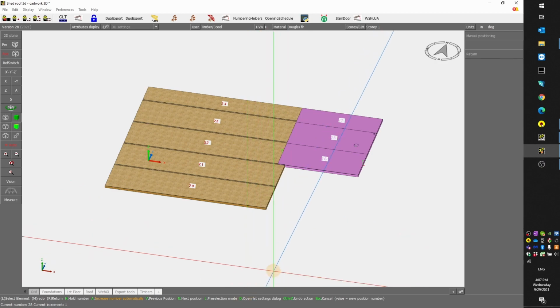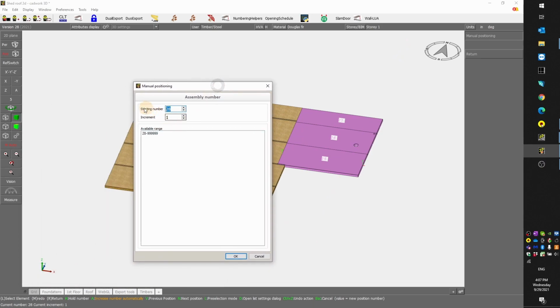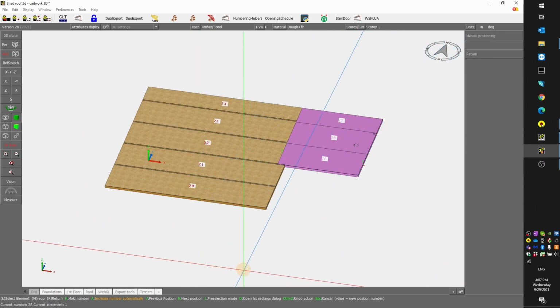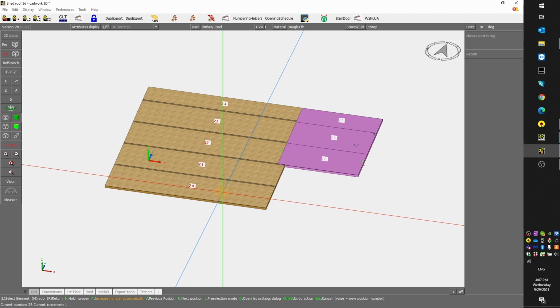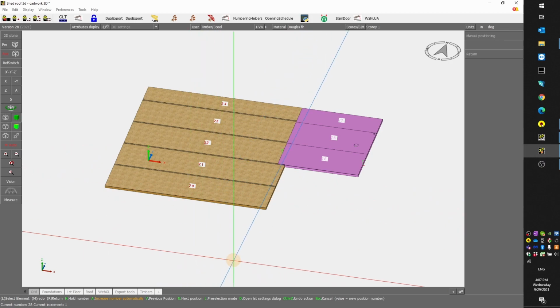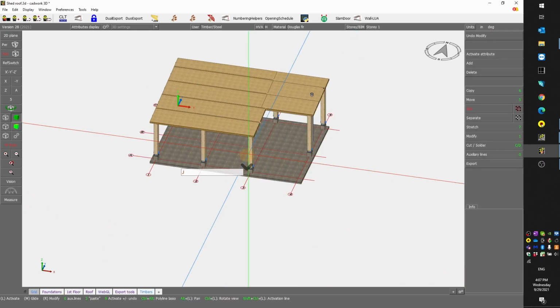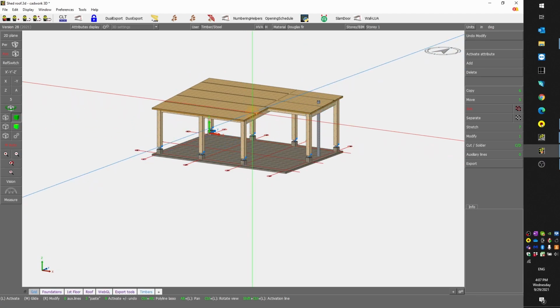You see you can press D, so you have some shortcuts. Here you could change the starting number and start with different panels or whatever. So there are some options. If you make a mistake, you can press V or N for the next one to jump and increment by 1. That can be done. So there we go. We have our installation number or assembly number defined.